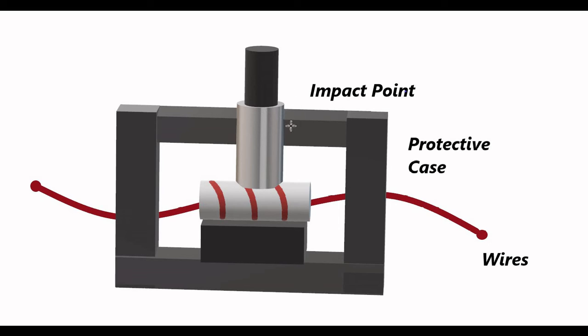As I said, the design principle is the same, where we have the ferromagnetic magnetostrictive material designed in the form of a solenoid or toroid placed in a platform that kind of channelizes the whole application of force or pressure or stress at the impact point towards the ferromagnetic material.